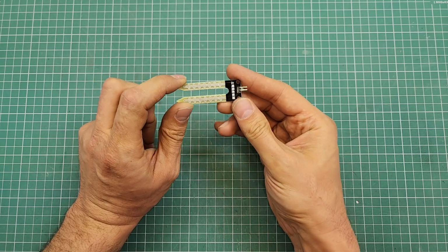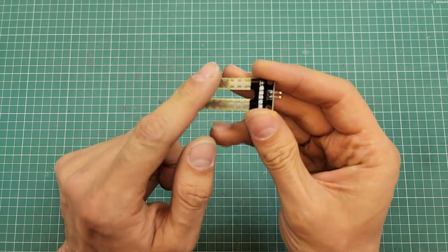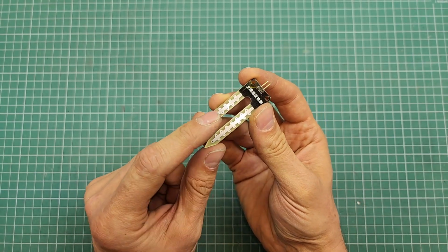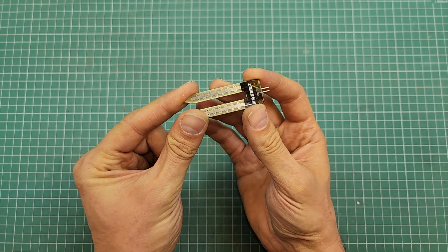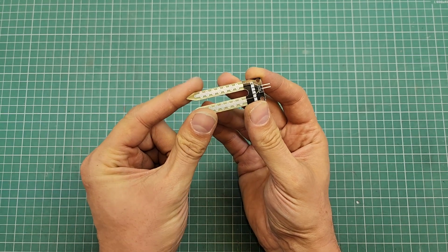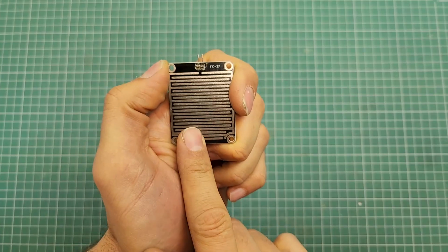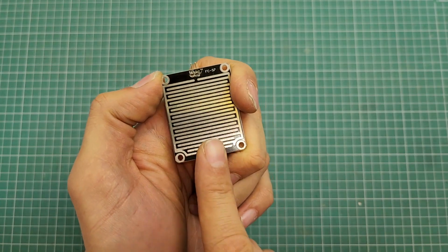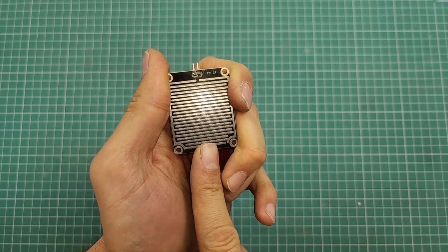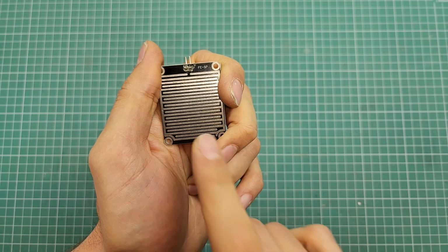We have to insert the sensor into the soil and then measure the resistance between these two electrodes. As the soil moisture increases, the resistance between these two electrodes decreases, and as the soil moisture decreases, the resistance between these two electrodes increases. This is a rain sensor. We have to place this component in a location where if it rains, the raindrops will hit this component and cause the resistance between these two electrodes to decrease.